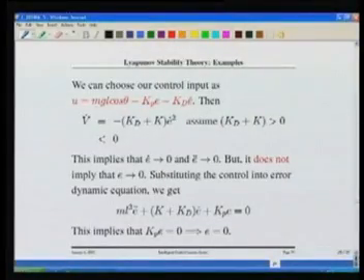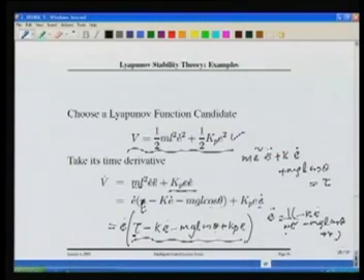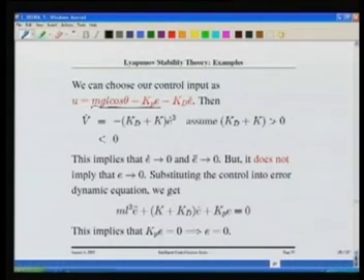So, obviously, if I simply make u equal to mgl cos theta minus k p E, then in the previous slide we saw that V dot can simply be equal to E dot minus k E dot square, but that does not guarantee me asymptotic stability. You will see that, and that is the reason why we added another term, minus k d E dot. By doing that, V dot becomes minus (k d plus k) E dot square.